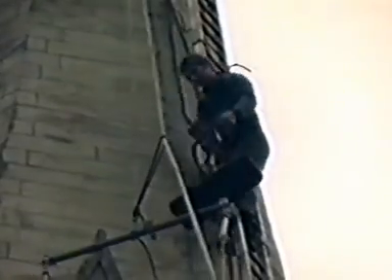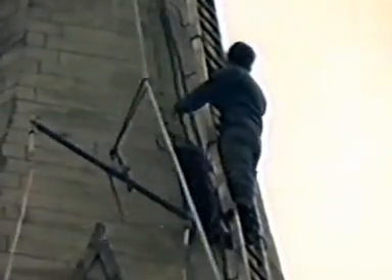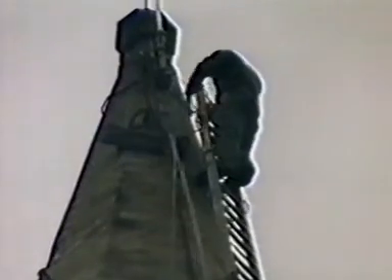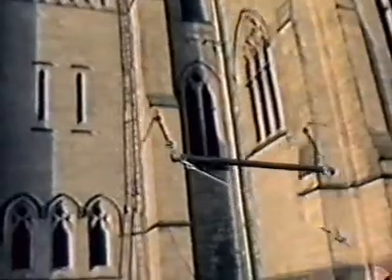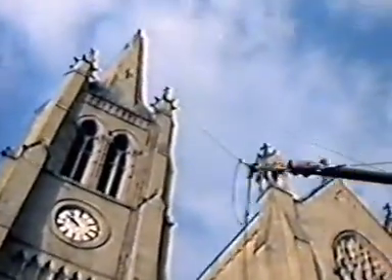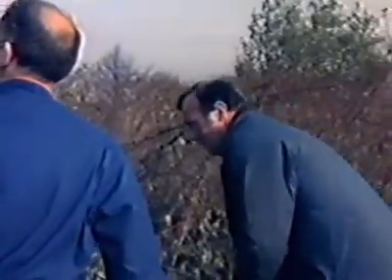The church steeple happens to be roughly the right height. It's about 50 meters. And what we've done, we've simply got a steeple jack to go up to the top, a job I wouldn't like doing, with a copper wire. He's attached the copper wire to the top of the steeple, and it's brought down to the ground to a firm anchor, and it's stretched. And then that bottom part is connected to the transmitter.